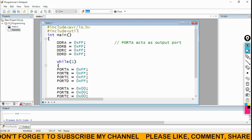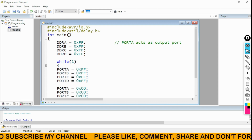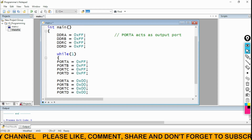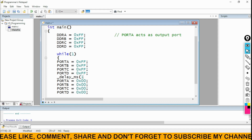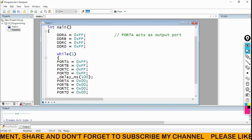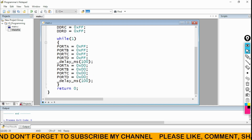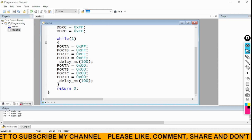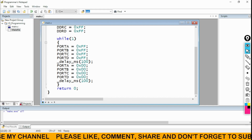For that, I'll include a header file called util/delay.h. I'm going to introduce here _delay_ms, which is an inbuilt function. I'll take 100 milliseconds according to this particular header file. I'll again clean to remove all the files, then make all the files.